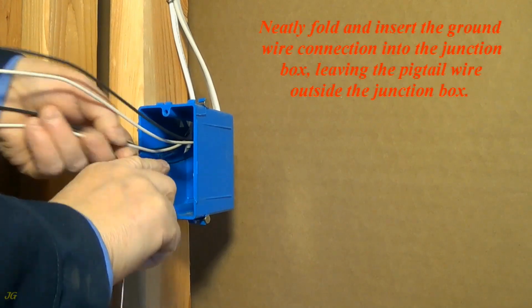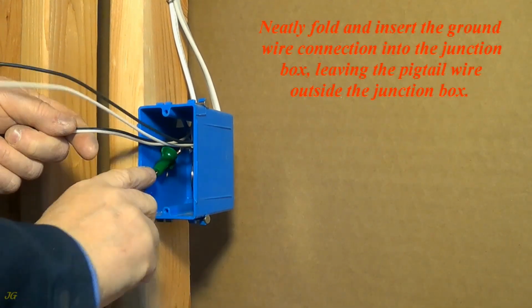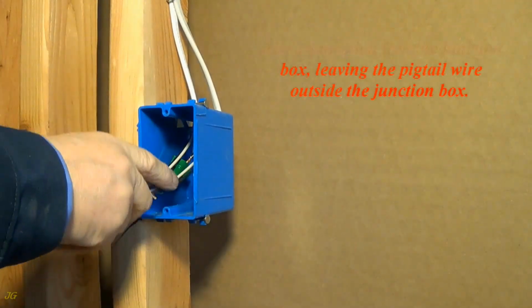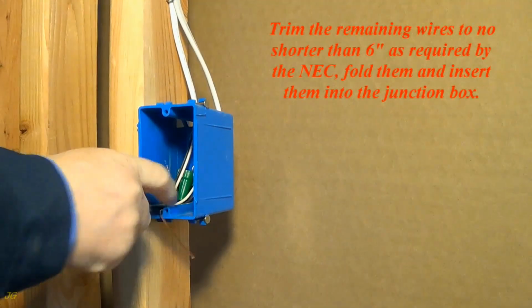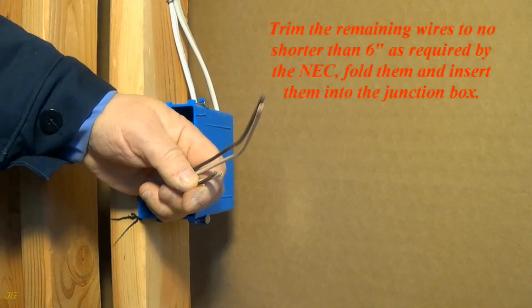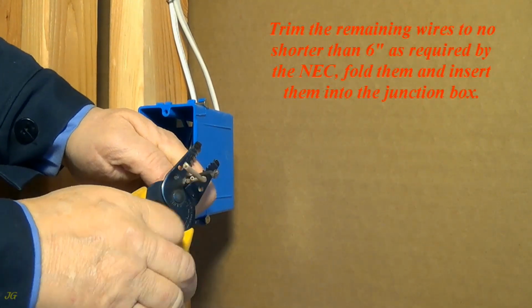Neatly fold and insert the ground wire connection into the junction box, leaving the pigtail wire outside the junction box. Trim the remaining wires to no shorter than 6 inches as required by the NEC, fold them and insert them into the junction box.